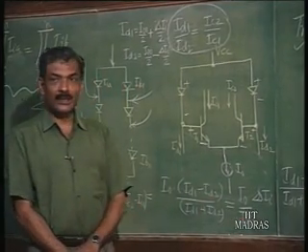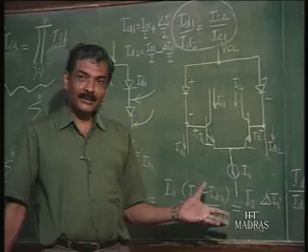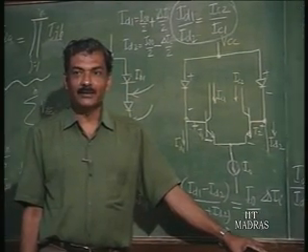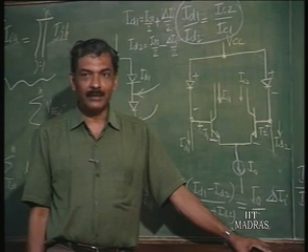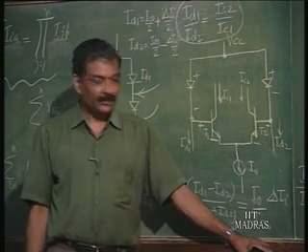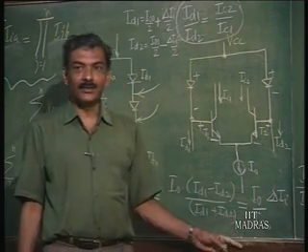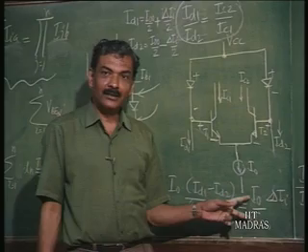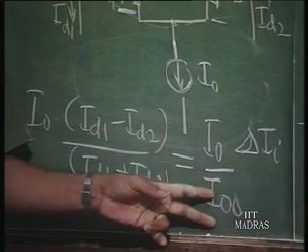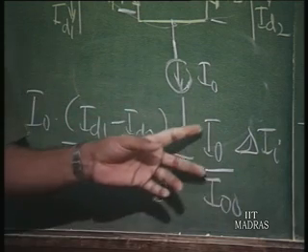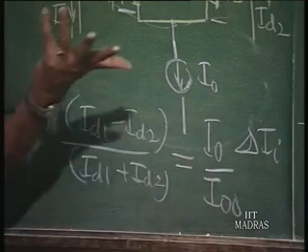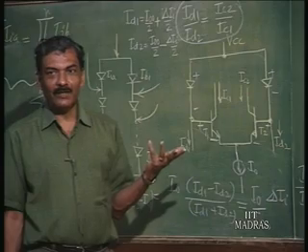This is unique because such constant gain we could only obtain in other schemes by giving negative feedback. This has no negative feedback. This is independent of temperature, active device, anything. This is dependent purely on current ratios. How can I get a current ratio like that? I use current mirrors. Let us say a 1 milliampere current mirror, I use 10 times in shunt, I get 10 milliamperes. So, it will be an absolute constant, independent of temperature and all that.